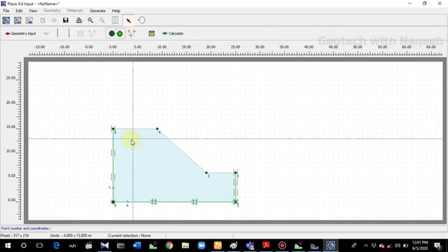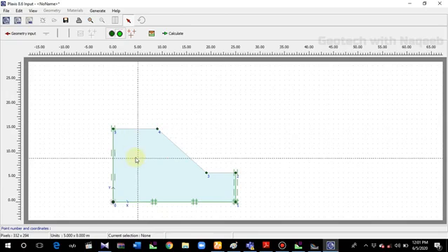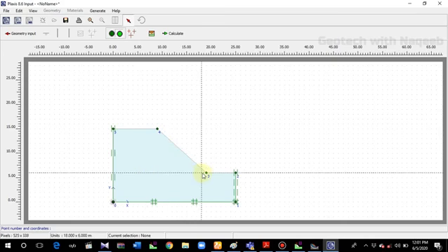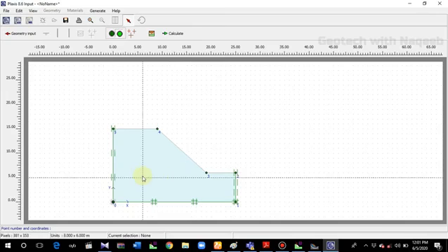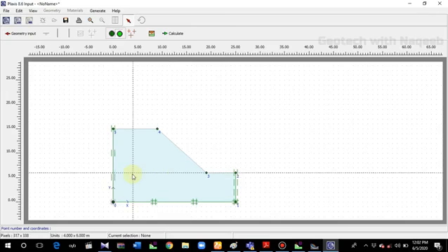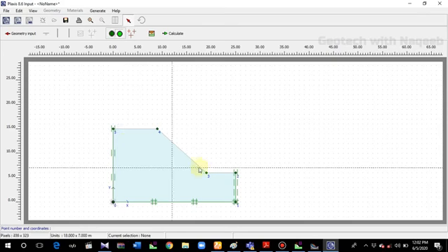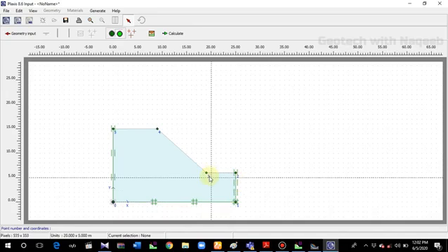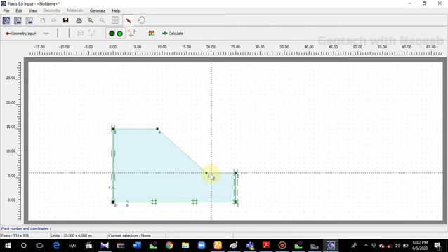We'll switch to the initial stresses mode. Here is a very technical concept. You need to understand that since I'm modeling just a homogeneous embankment and my purpose is to analyze the slope stability, but in actual you need to be careful while designing or analyzing the embankment from Plaxis software, because if you're using the staged construction, in staged construction initially there is no construction of embankment, so you need to apply the initial stresses over this portion from this surface that is assumed to be a ground surface level.